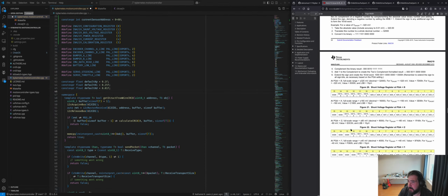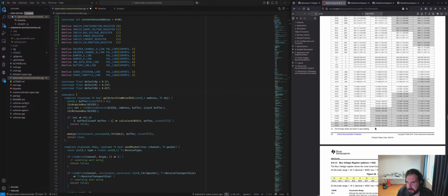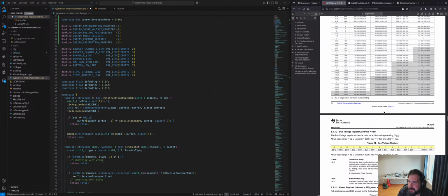Basically everything's divided by 100, so the output is in millivolts, but divided by 100. So 32,000 is 320 millivolts. Because it's a 16-bit register, you could technically have values from negative 32,768 to positive 32,767. So it's literally just a two's complement signed fixed point measurement. Okay, so that's easy. That's just a long method of saying that, I think.